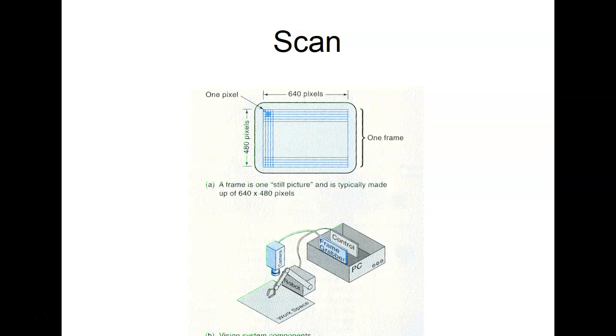So what the camera does, at the end of every horizontal line, it gives us a pulse. We call it horizontal sync. And then down here, when it hits the bottom, it gives us a vertical pulse. And so this camera generates these synchronization pulses. And as soon as this comes into your monitor, it automatically gets in sync with the camera.